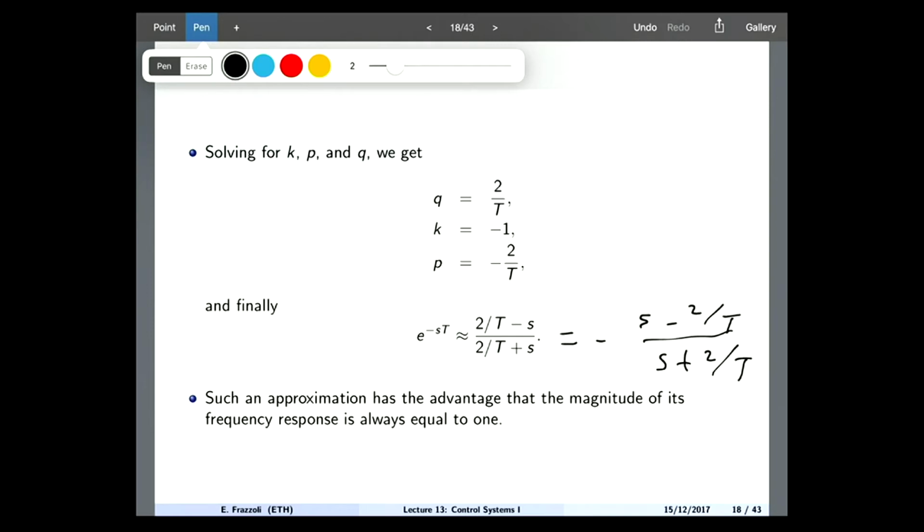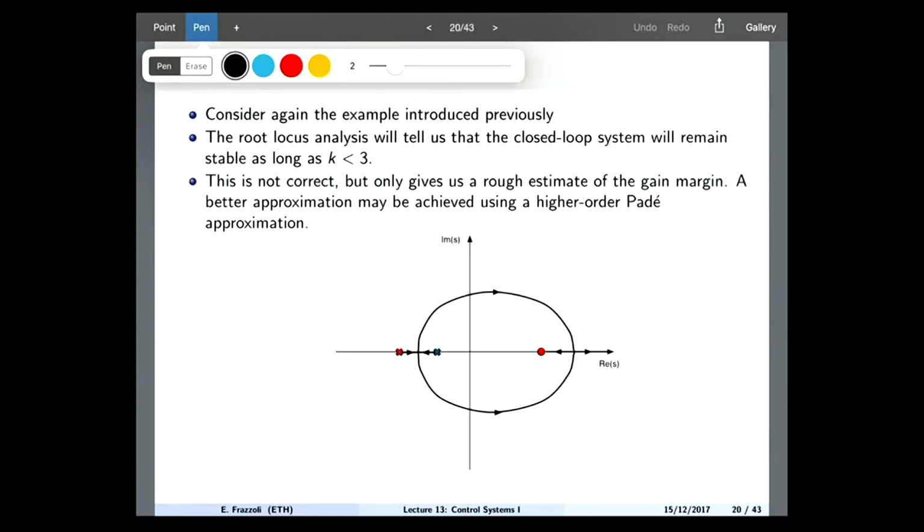Okay, what you see now is that we have a transfer function written in the root locus form. And what you see is that the gain of this transfer function is actually negative. So if I have a positive k, what is the root locus gain? It's negative. Okay? And that's why we get this root locus plot. In this particular case, the answer to your question is that the time delay essentially makes you look at what you would consider the negative k root locus usually.